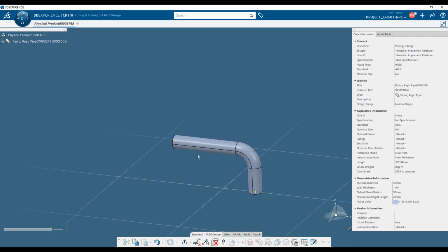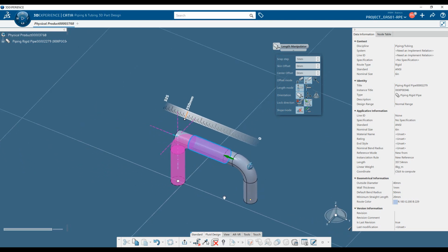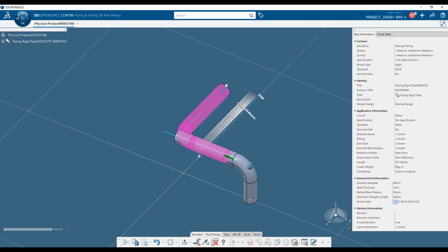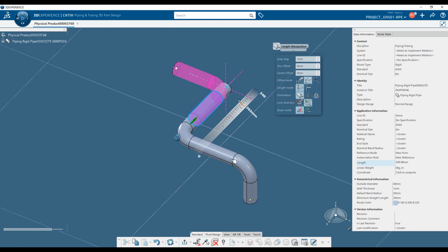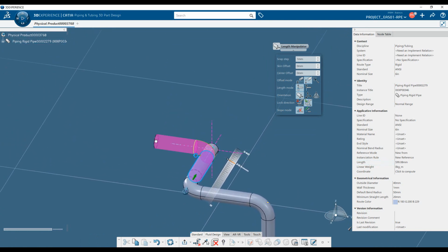If you want to continue the pipe, you just reselect the last node and you can continue the pipe and select the dashed line that pre-indicates the direction to follow and continue to create a new point. If you don't want to respect those directions, the normal direction, then you can access the orientation manipulation.